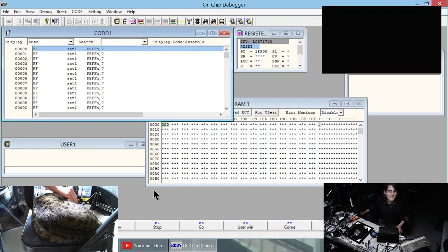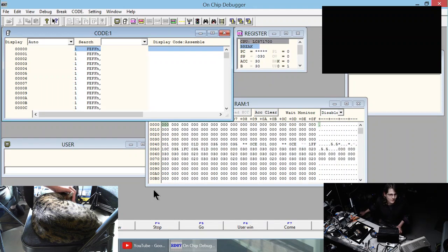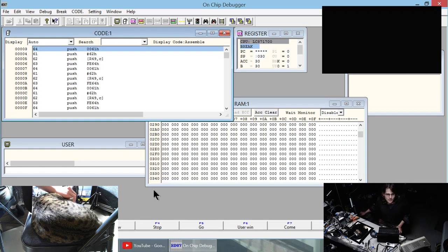Check that out. It's like an old school terminal emulator filling up the screen. And so that RAM view does not look right, I think. Oh, I think what's going on there is I'm probably implementing that read by sending back a shorter packet than the host expects, which the debugger is then not really handling correctly, and it's filling in just garbage memory.